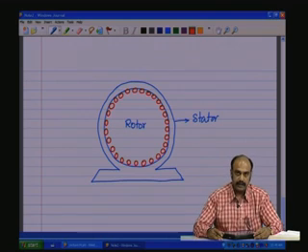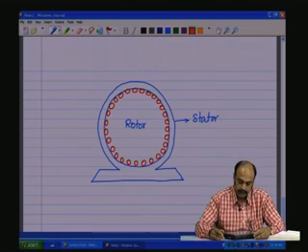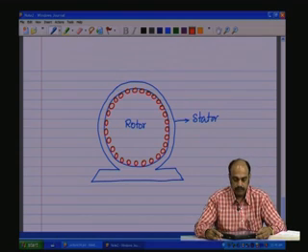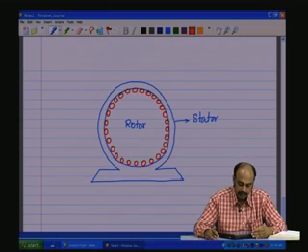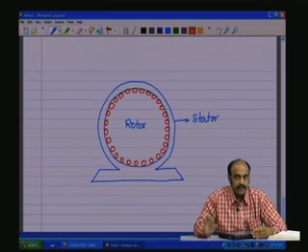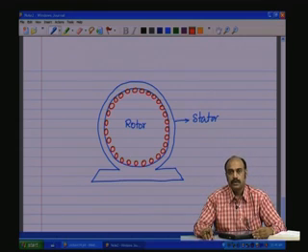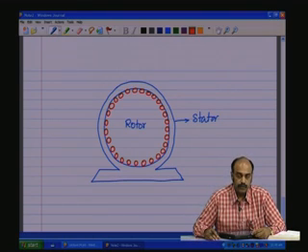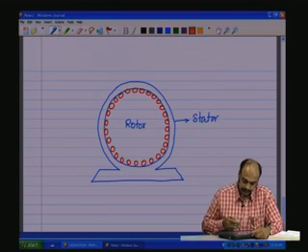That is why the name, the squirrel cage induction motor. In the wound rotor, the rotor coils are brought out through slip rings and brushes, like in the DC machine, but through slip rings, not commutator, mind you. This means the current in the external electric circuit is also AC.